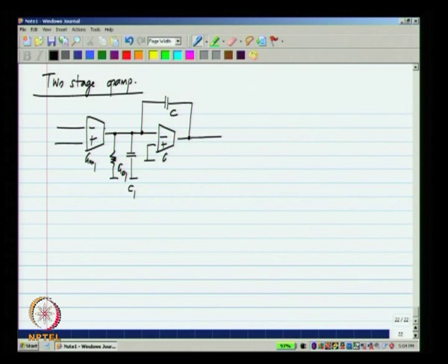And the second stage has a transconductance GM2, an output conductance GO2, and a total capacitance of CL which can be due to transconductance itself and any load that is applied to the op amp, and there is a capacitance C which is around the second stage, and this is the integrating capacitor, that is the current from GM1 is supposed to pass through this and give the integrating function with a unity gain frequency of GM1 divided by C.